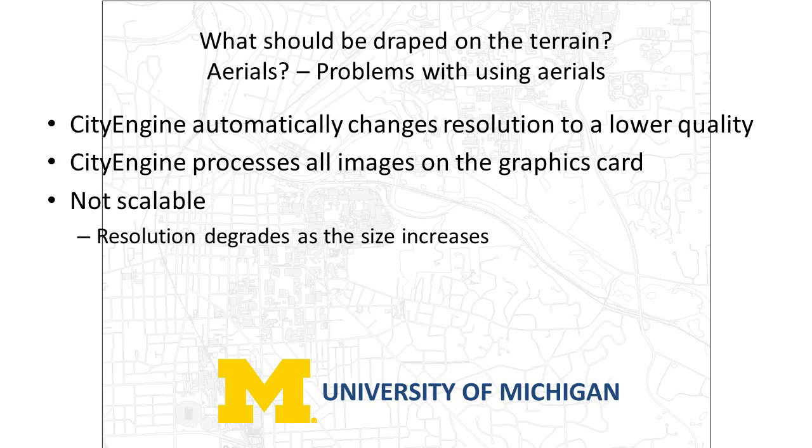When you're going to build a campus, you shouldn't start with a small test area. You really should start with your largest extent and see how well the package you're looking at handles that largest extent, and then you can work your way down. If you start with a small extent, the package may not be scalable up to full size.